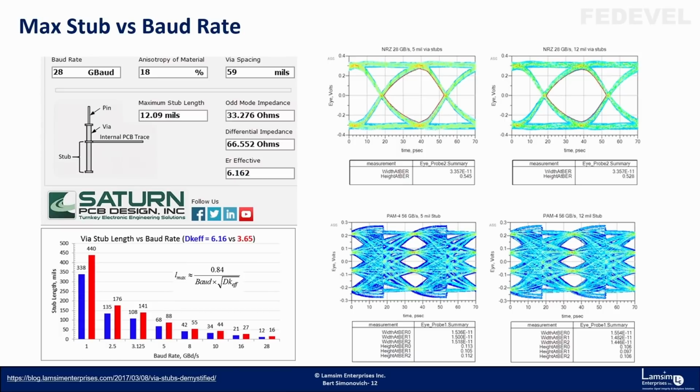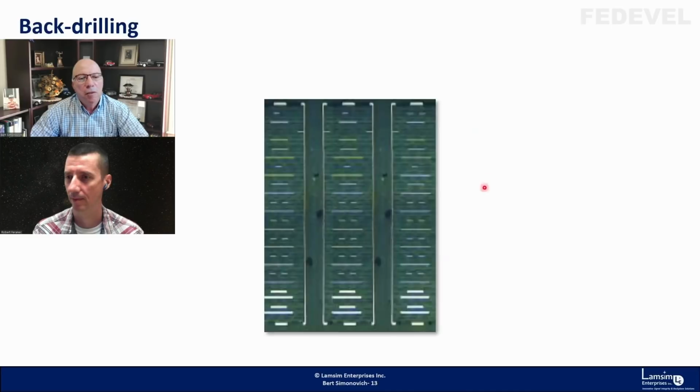Before we leave the vias, I have a couple more slides. This is sort of what backdrilling looks like. In this picture, we have a differential via, or 2 vias, and you have the top and the layer near the top. And actually, this is the cross section of that long via. We measure it if it has a via stub that long.